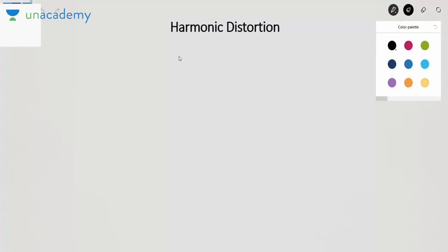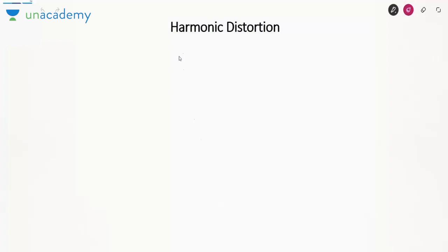Out of that, what is most important for our case is nonlinear distortion. Based on nonlinear distortion, as I have told, harmonics will be generated in the output, or you can say the signal will be non-sinusoidal, due to which it can be expanded as a Fourier series. So if we have an amplifier with an input voltage Vi and output current, suppose IC, then this IC will have a DC biasing current plus the non-sinusoidal output current, which can be expanded in a Fourier series like this.